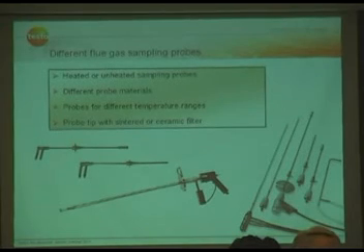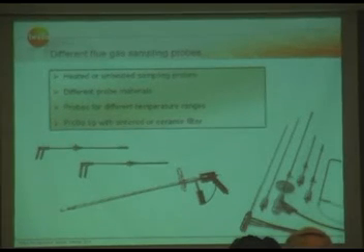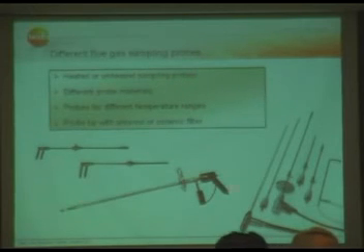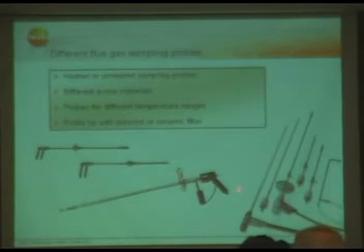TESTO is providing different flue gas probes for different applications. We have heated and unheated sampling probes. Like this is an industrial probe with a heated handle, a heated pipe. Sometimes necessary, you know, if the wall of a stack is very thick and you have to make sure that your SO2 reading or NO2 reading has to be very accurate, because SO2 and NO2, specifically those two gases, they react with the condensate in the flue gas very fast.